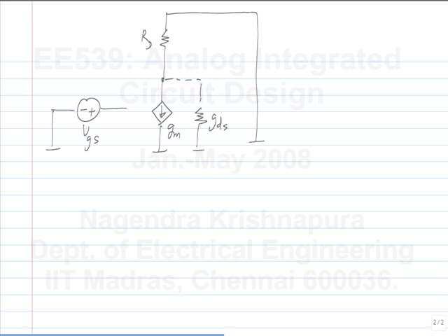So, in triode region, two things happen. Firstly, the GM falls down and GDS increases. So, we had earlier made the assumption that all of this incremental current goes through RD. That will not be true in the triode region, and GM itself falls down. This is the reason why we would like to have amplifiers operating in saturation region.